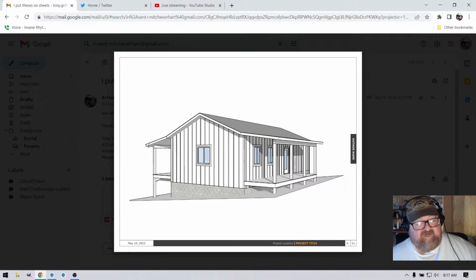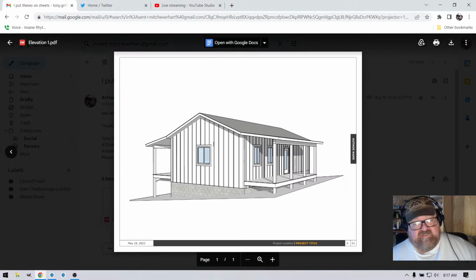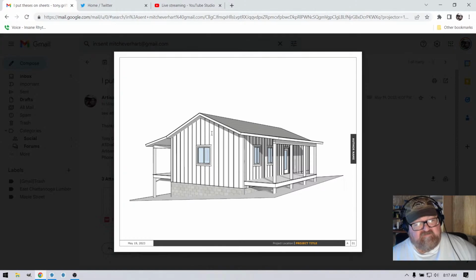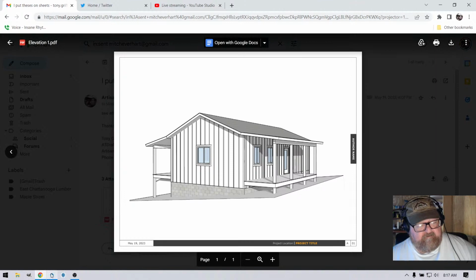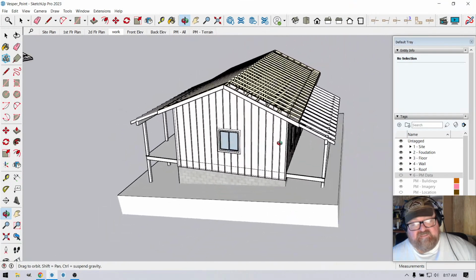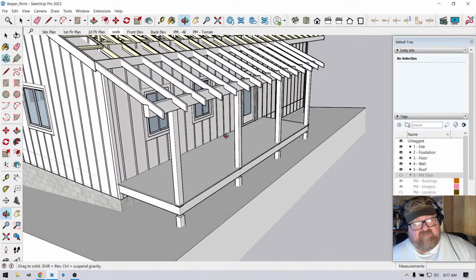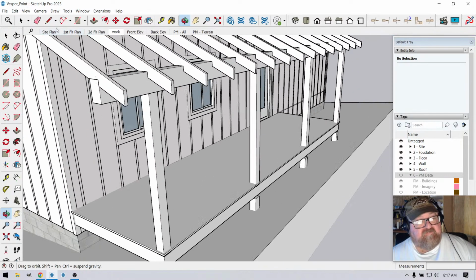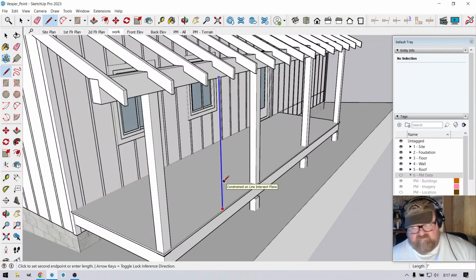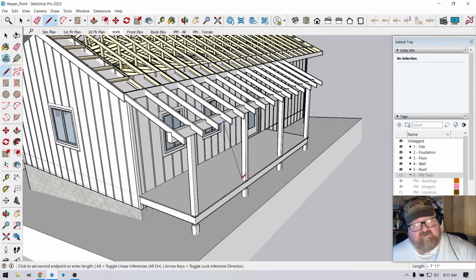He didn't like this break in the roof, and he's right. There's a maintenance issue. This is a heavily wooded area, and you'll get leaves trapped there. But usually the reason you see this is because, and I'll go back to the model, we like to keep a 7-foot clearance under the beam, under the porch beam, right? So what have I got? I've got 7 feet.